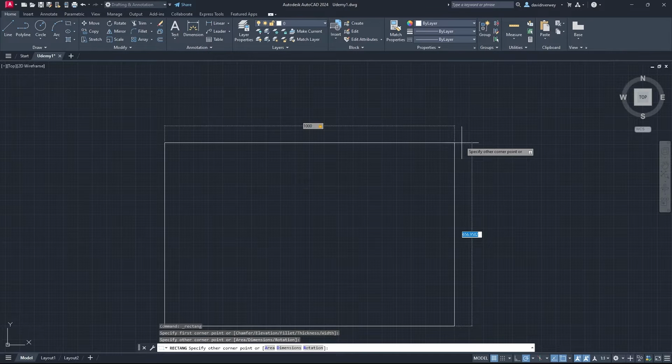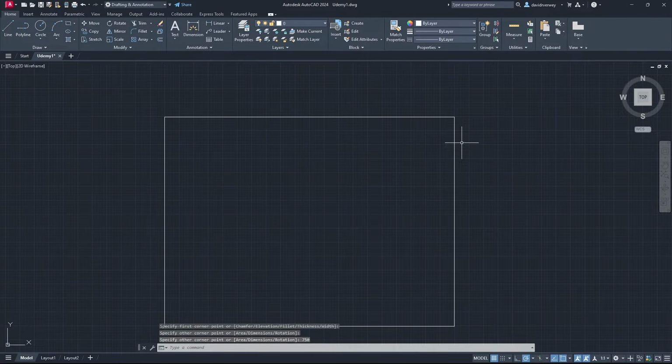Press tab. You're going to see that there's now a lock beside my 1000. The lock means that my size is locked in, and what that does is it prevents me from creating errors in that axis. So what you're going to see now is I want 750, and you're going to notice after I pressed tab that the other axis is now highlighted and I can adjust it. So I'm going to put 750. Once I have done that, I press enter, and my shape, my rectangle, my square, whatever I'm drawing, is at the exact dimension that I want it to be at.